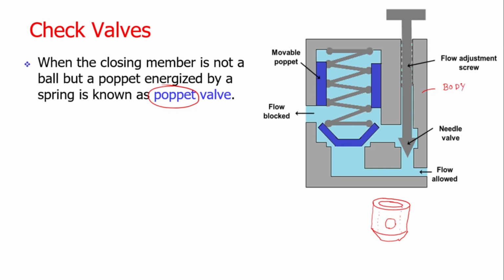It's having the internal spaces or the grooves. So these are the internal spaces. The blue color spaces are seen here. Inside the major space provided in the check valve, we are having the poppet. The poppet is movable. Inside the poppet, we are having the spring of sufficient stiffness, and that stiffness of the spring itself is deciding the pressure to be applied during the flow.